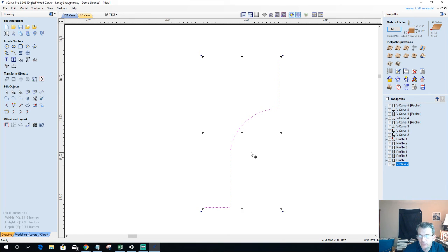And yes, Grant, you could use a pointed roundover bit, the one that's almost like a beading bit, has the roundover, then it has the nice little bead point in the center. Absolutely, that's also a form tool. You've got to draw out that bit and add it to your tool database. But whatever that is, it's just a profile cut, and you're stepping over.